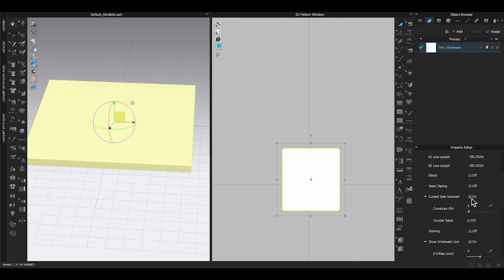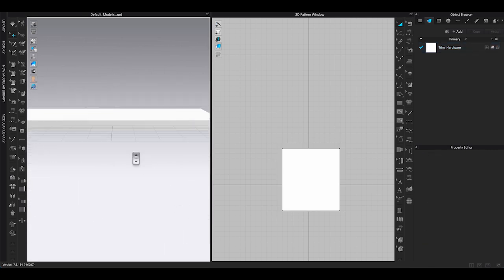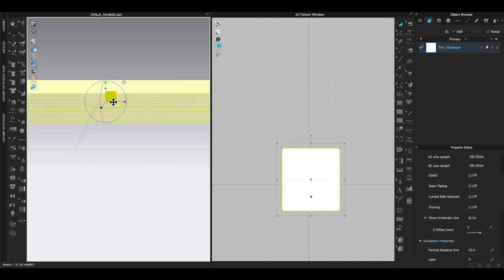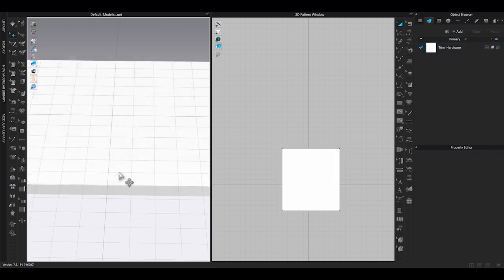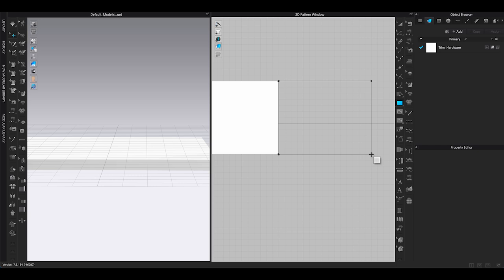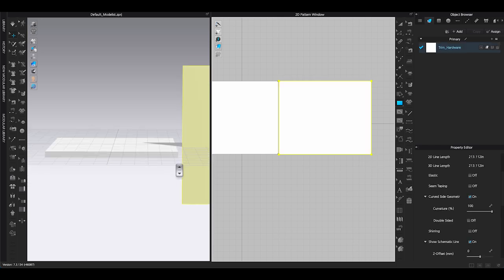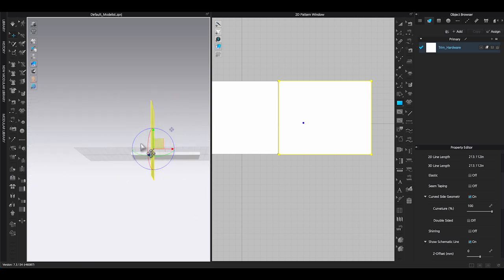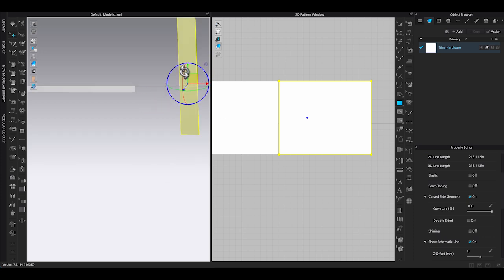Once you add thickness, part of the floor pattern is above ground grid. Make sure to use gizmo to move the piece right below ground grid. This way, when you bring out avatar, the avatar's feet will be above the ground. Next, I will create a second rectangle for the first wall. Use gizmo to rotate this piece to 90 degrees and add thickness rendering.